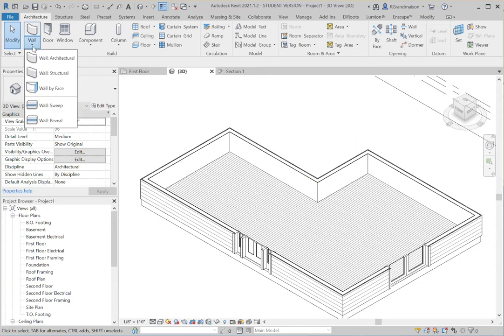So it's under the wall tools, and the reason why is because this actually is an element that, unlike say a sweep, if you were to do a sweep by a component in place, you would have to physically cut the openings for the doors and windows. And in this case, because it's part of the wall, we won't have to do that. They'll automatically stop and start at the door and window openings. So I'm going to go ahead and go down here to a wall sweep.